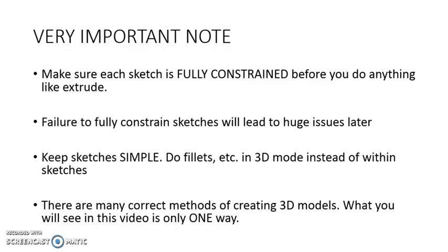You're also going to see, not necessarily in this video, but later on, that I like to keep my sketches simple. We're going to do as little as possible with each simple sketch. Instead, use things like fillets and chamfers and so on and so forth. Those are going to be done in 3D mode instead of within the 2D sketch.